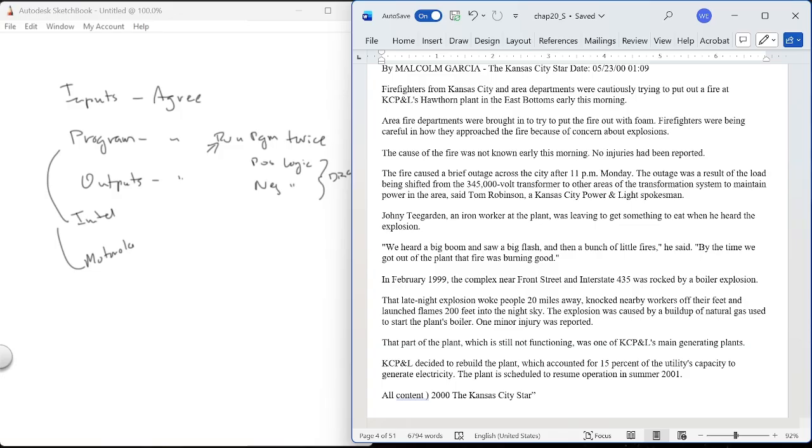My suggestion is to turn to that BGIA book and start looking there and start asking questions. But do not say that you have to do everything ahead of time. You have to do what you can do ahead of time. But after the fact, if you still see safety issues, if you have a safety PLC, you can confront them and you can actually program them in. If you don't have a safety PLC, you're dead in the water. You have to have a safety PLC to program safety items.